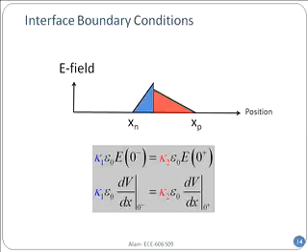If you have charge between the base and the emitter, let's say a defective layer, you have not been able to grow it very well, then D1 minus D2 will be equal to the charge that you have in the interface. If you do not have any charge, then these are the relationships. That's what you're assuming.